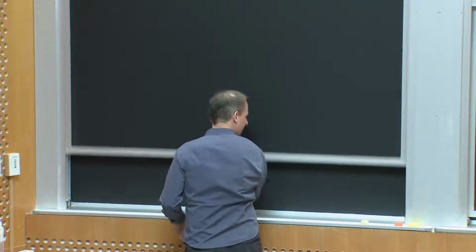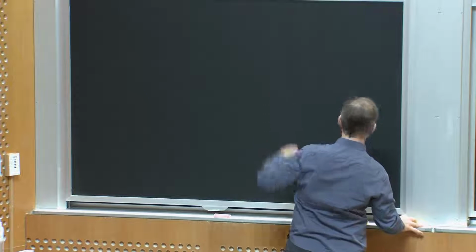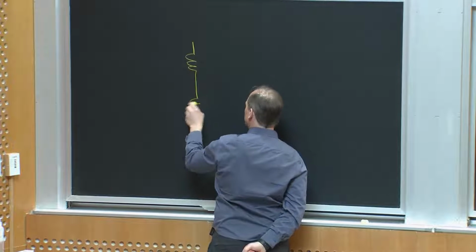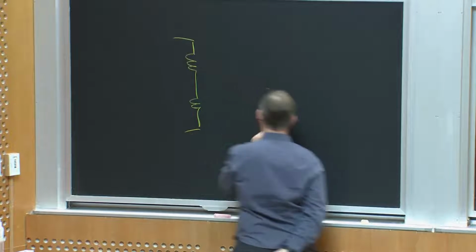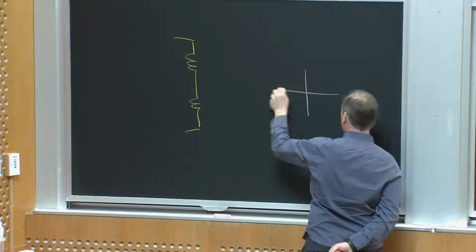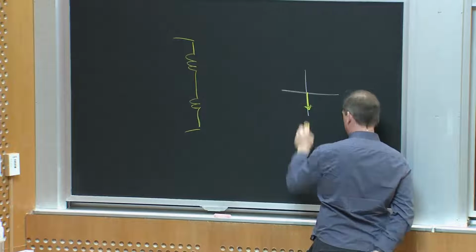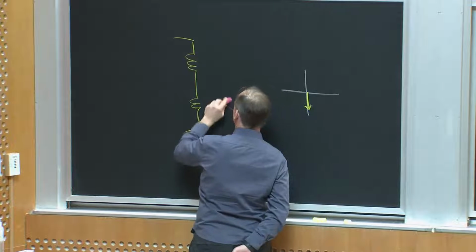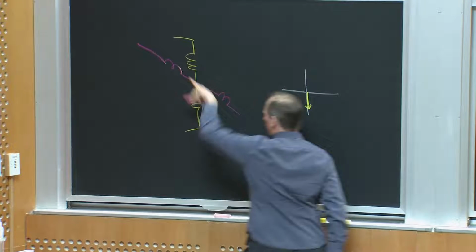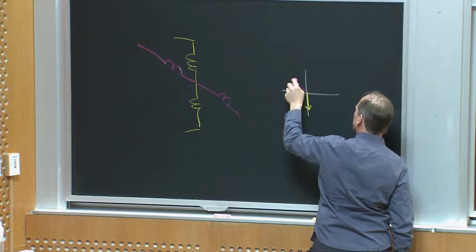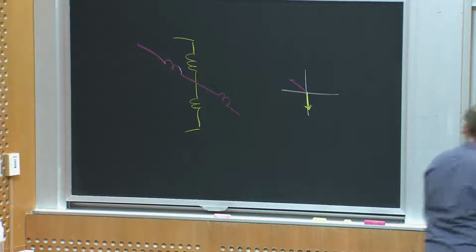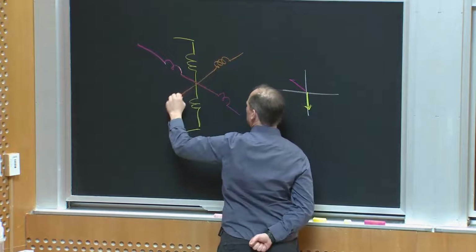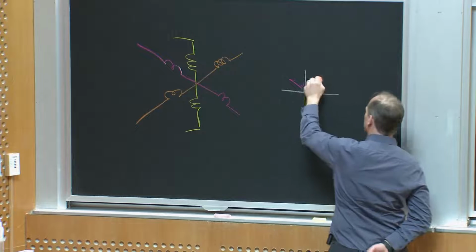So you could imagine putting in, instead of having two coils that are 90 degrees out of phase, a first one that generated something like this direction, a second set of coils to generate a second direction like this, and a third set of coils overlapped in space that would generate a third direction.